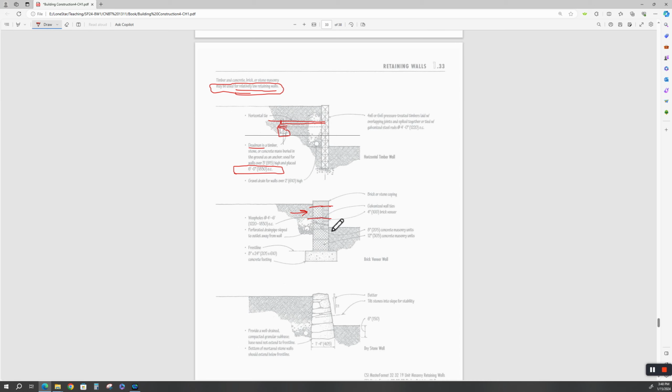And I don't care what kind of mortar you use, it will eventually leach out. But depending on how much hydrostatic pressure is behind here over the years, you will need a vapor barrier on this, which means you'll need to paint the back of this with coal tar epoxy or line it with something heavy elastomeric, and then seal your weep holes.